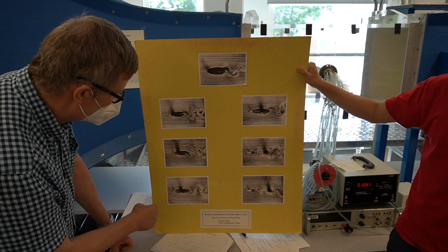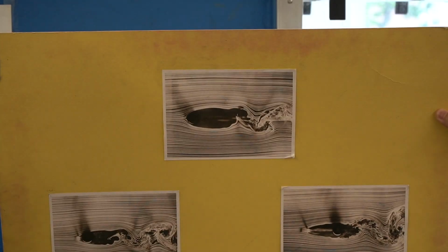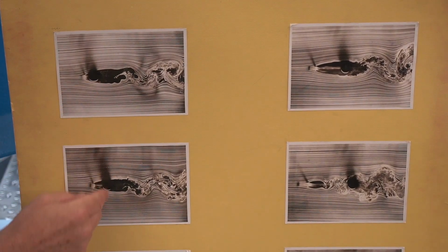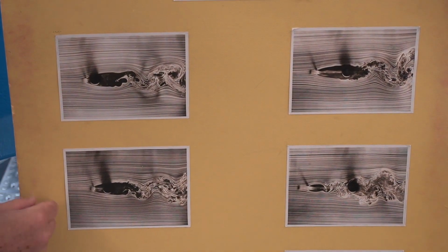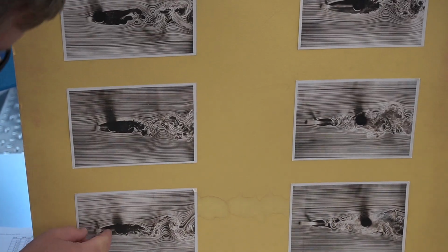And I think as you increase the distance between the circular shape and the little plate that is further upstream, you can see as we go down here, the position of that plate moving further to the left, and the cylinder moving to the right. You're getting a region in between the plate and the cylinder that doesn't have this unsteady vortex shedding, the creation of opposite sign vortices one after another. It doesn't have that until this gap is sufficient to allow these alternating sign vortices to occur. So here they're nice and steady.